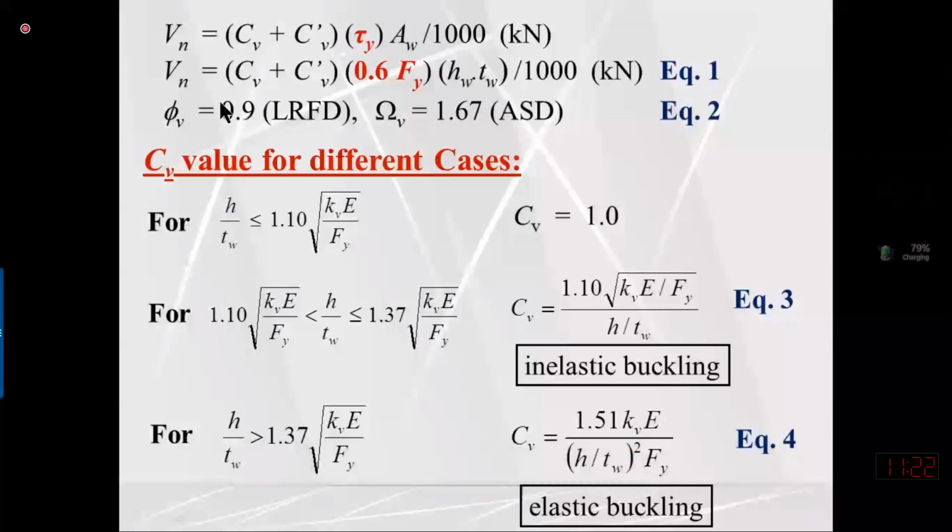If we are given the design of a plate girder, meaning we know the flange size and the web size, and the spacing and size of stiffeners are given, then we can determine the total shear resistance or shear capacity of the web with and without tension field action.